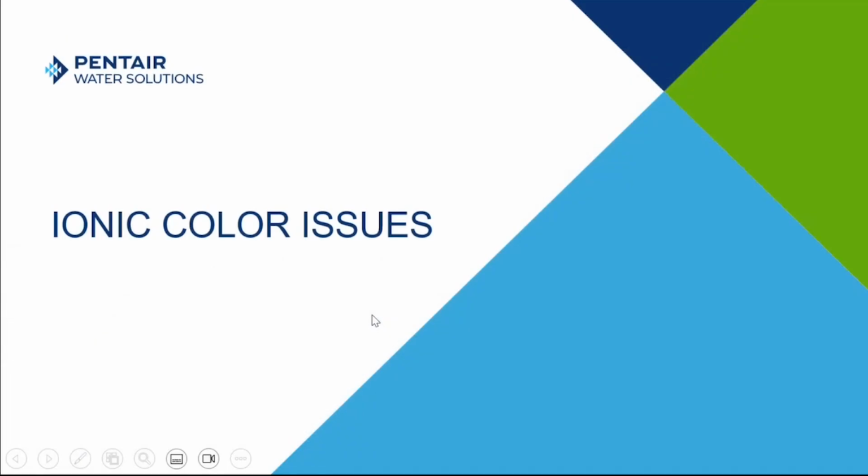Now, ionic color issues, this is where ion exchange is going to shine in resolving these issues. Most of the time when we see ionic color issues, it's due to aggressive waters dissolving things either in the well strata itself or in the municipal system. So understand pH, low hardness, super soft waters can contribute to ionic coloring.